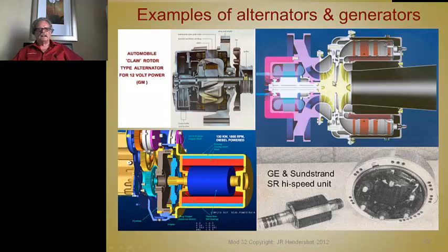Intake air comes in here, and then it passes over into this chamber, which has ignition and fuel, and so that high pressure air combusts with the fuel and causes a very high pressure, and that drives this turbine, and there's the exhaust. So the compressor turbine is connected to the combustion turbine. This compresses the air, and the air then burns with the fuel, and then the high pressure from that burning causes this to rotate. So it's a very nice system.